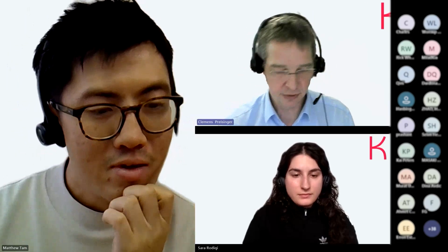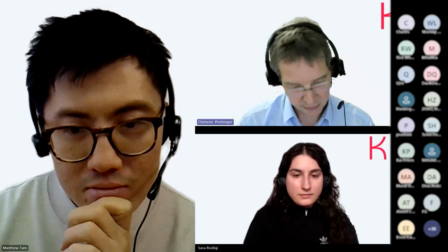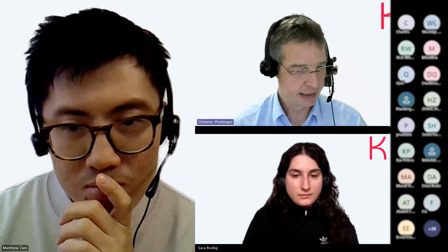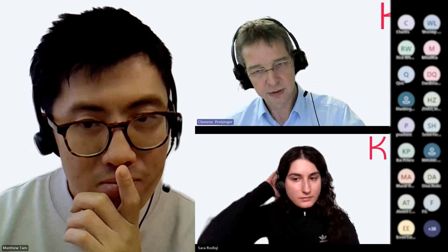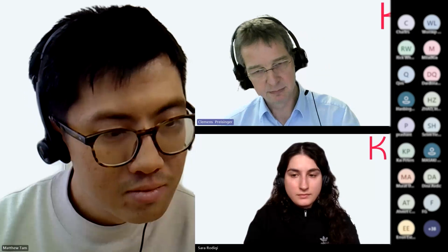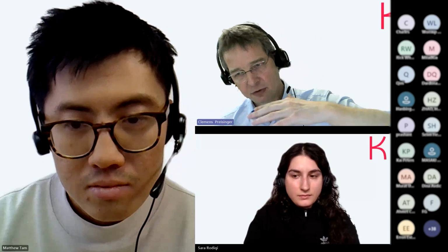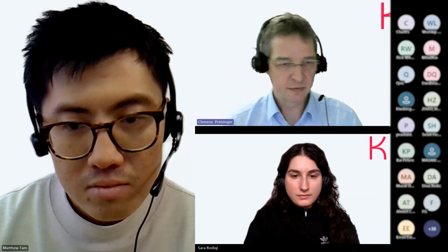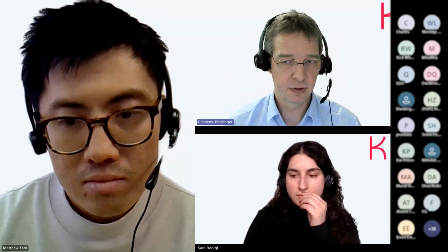And in this way, it comes close to a geometric nonlinear calculation. However, it doesn't include an iterative corrector step. So it might be that the displacements gradually shift off from the correct path a little bit. And for deformations, or for shape and form finding, it's maybe not so important.